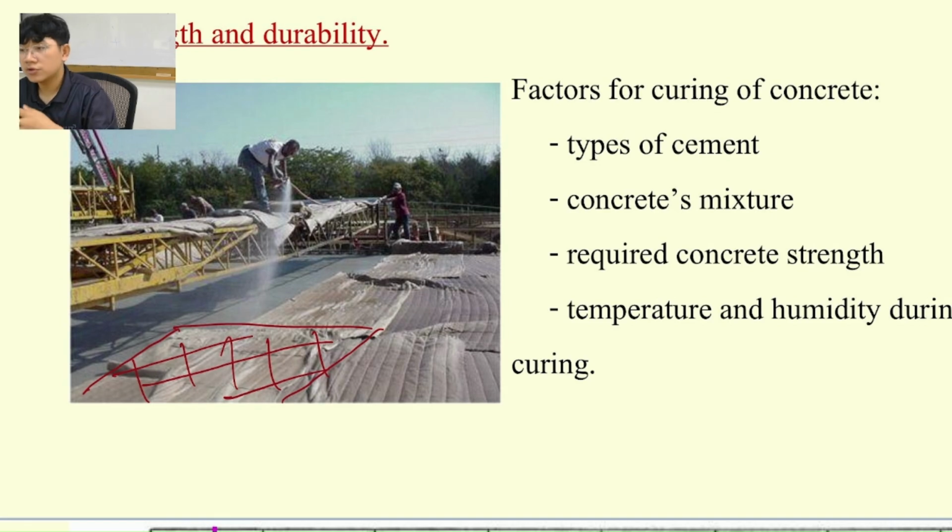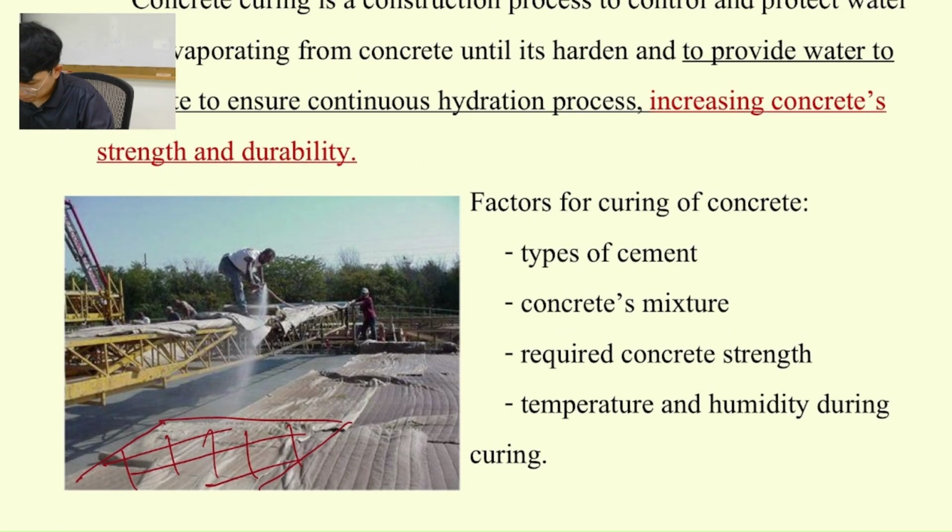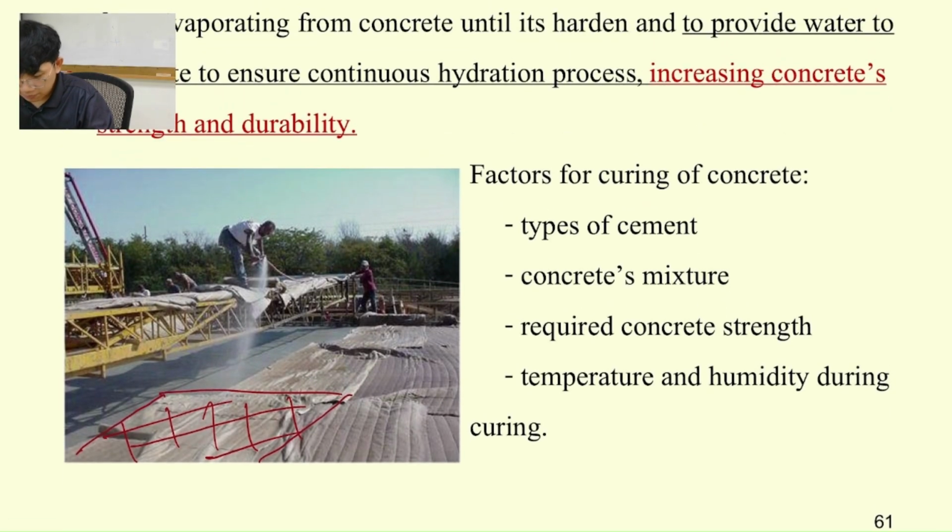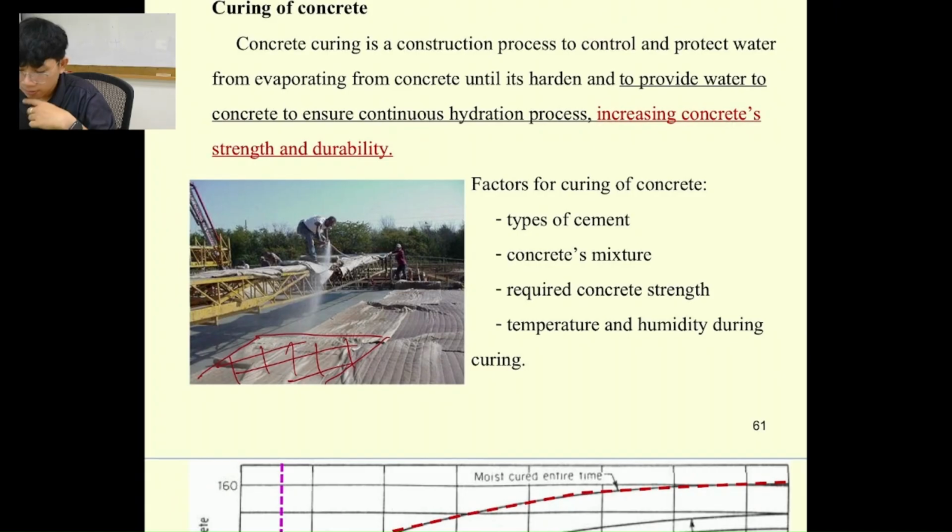This is one technique we use for curing in the field, because we cannot stay at the site and spray the water 24/7. So they just use the cloth and spray it to prevent water loss from the surface of the concrete. And then we have some factors for curing concrete.